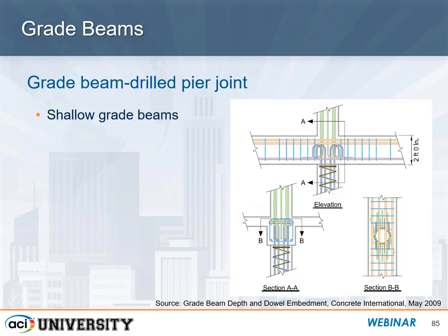And the last item I should say, is grade beams. There can be situations, either grade beam or sometimes a pile cap as well, where if the grade beam or pile cap is fairly shallow, you could get some congestion at the intersection of where the supported member and your foundation is coming in.